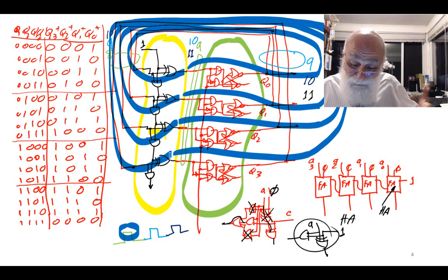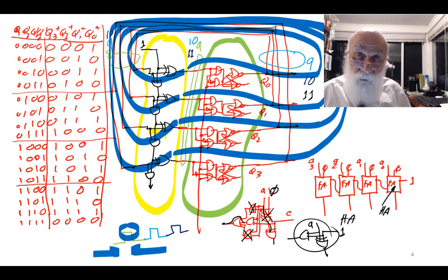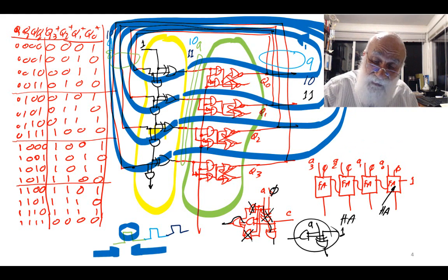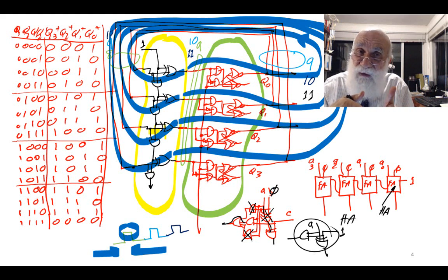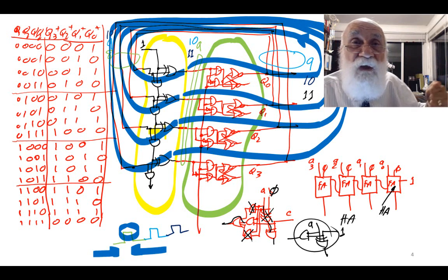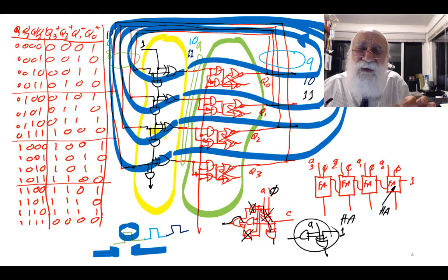What does that mean? What it means is if I keep my clock on too long, these blue lines are going to feed back, go through the incrementer, 8 becomes 9, and then 9 goes through the incrementer, clock is still on, and then 9 goes through the register, or through the latches, because it's transparent, becomes 10, 10 goes back, so 9 becomes 10, 10 becomes 11, 12, 13, 14, 15, 15 becomes 0, and then it keeps oscillating. Unless I know exactly when to stop it.